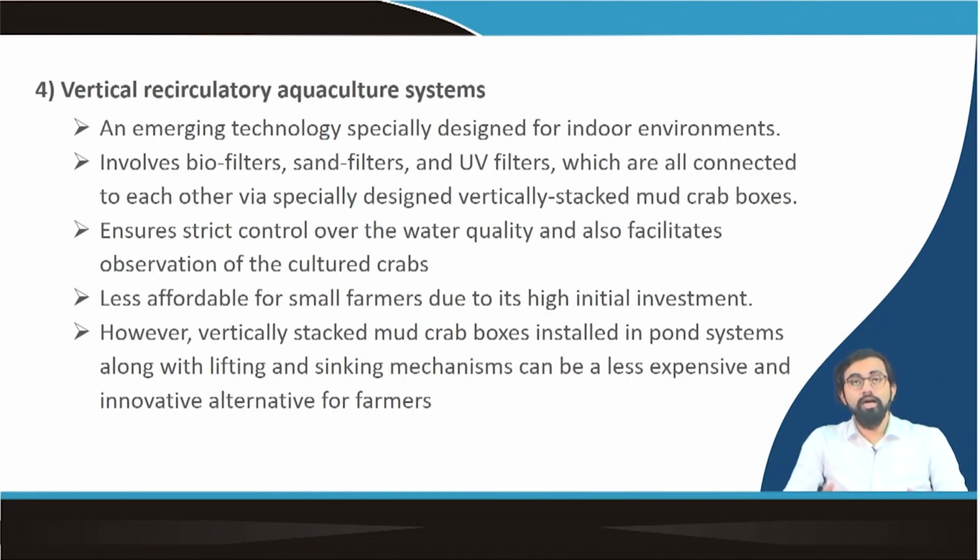In case of vertical recirculatory aquaculture systems, it's an emerging technology, where biofilters, sand filters, and UV filters are all connected to each other via specially designed vertically stacked mud crab boxes. They treat the water once it is utilized. After the crab culture, it's wastewater, right? That wastewater is again treated using all these filter mechanisms: biofilter, sand filter, UV filter. Each has its definite functionality, right?